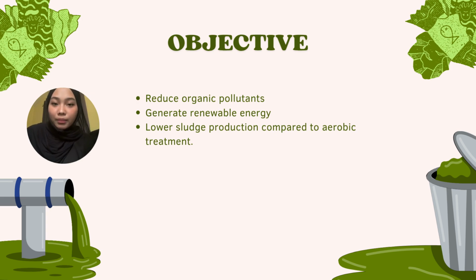Alright, next, the primary objective of anaerobic biological treatment is to remove biodegradable organic pollutants from wastewater, which is commonly measured by the reduction of chemical oxygen demand, also known as COD, and biochemical oxygen demand, also known as BOD. Another important objective is the recovery of energy through biogas production.